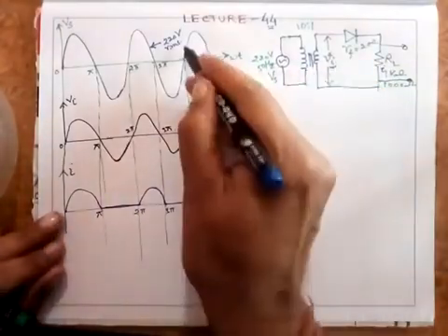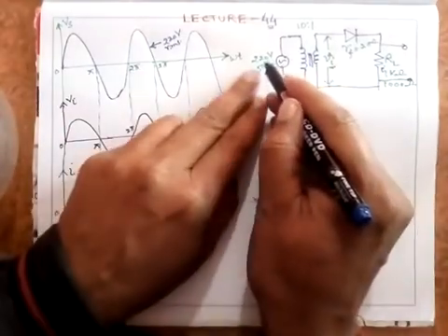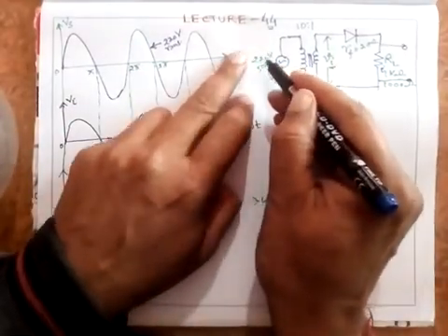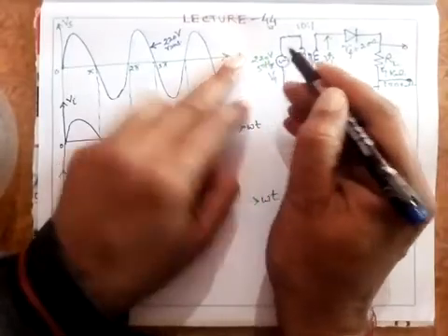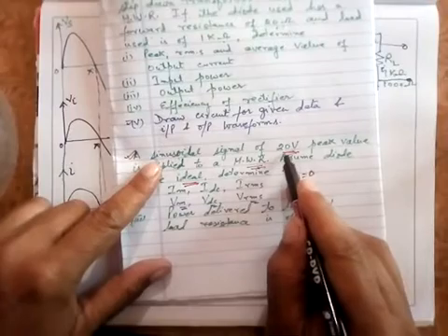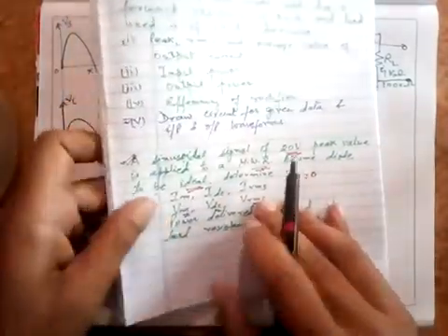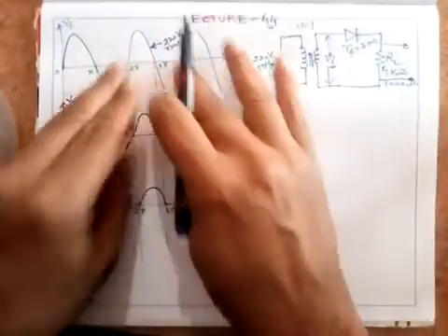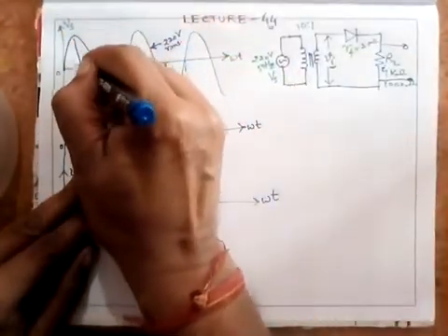Now look at this. When I say 220 volt, it means, suppose at your home your supply is 230 volt, it is the RMS value always. In the previous problems, if you remember, if a sinusoidal voltage of 220 volt peak value is mentioned, it is a peak value. Otherwise it is an RMS value. Now my point is, what is the peak value of this?